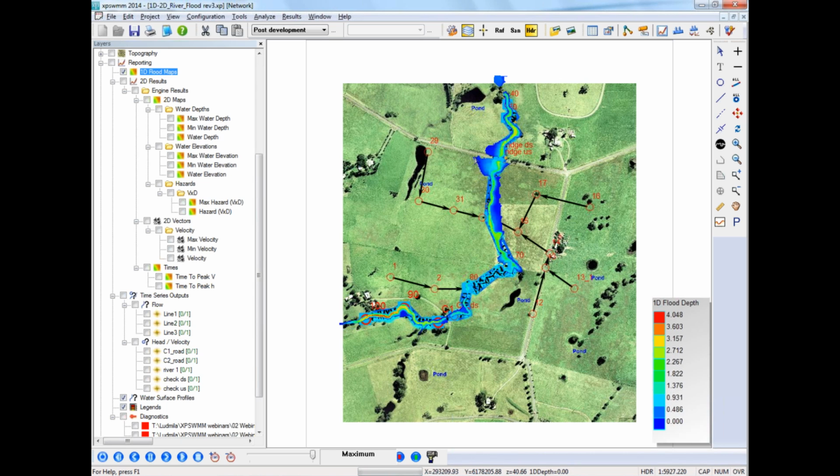But as Samra mentioned earlier on, this is identifying flooding at nodes, where you have these virtual basins. It doesn't give you the true representation and that dynamic flow over the surface, and maybe we have properties affected or farmland or whatever that we need to look at. We can see more information with the 1D, and I'll share another couple of views with you.